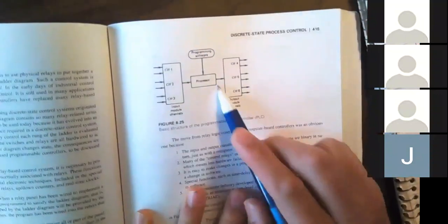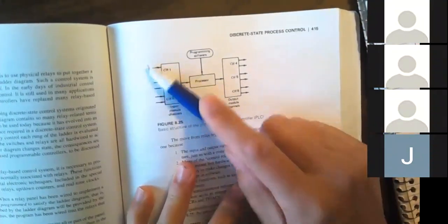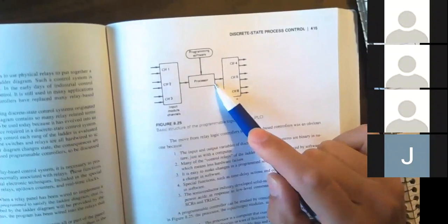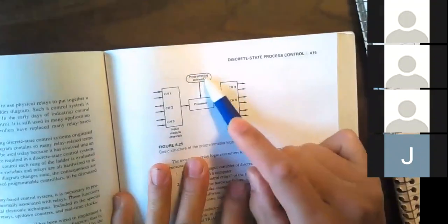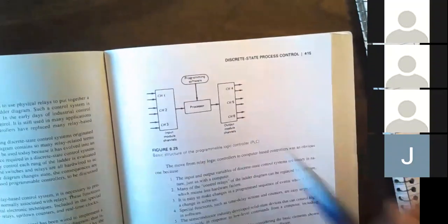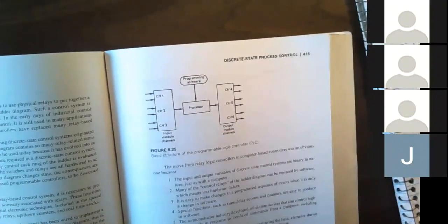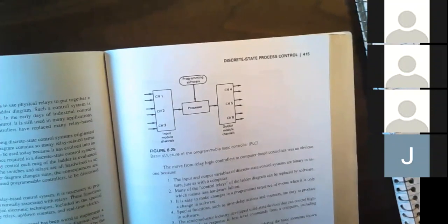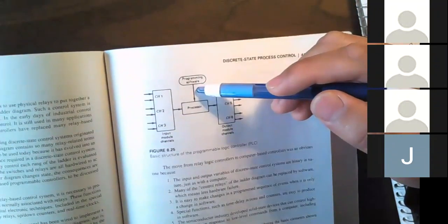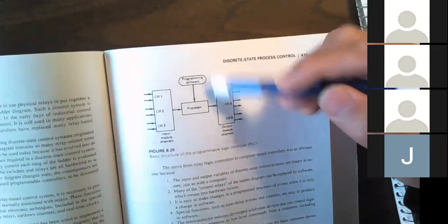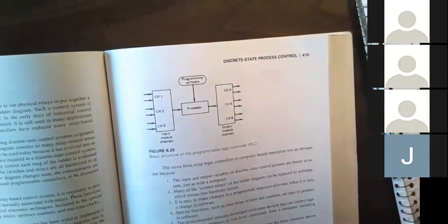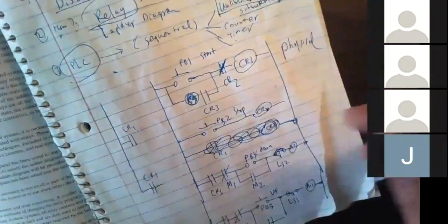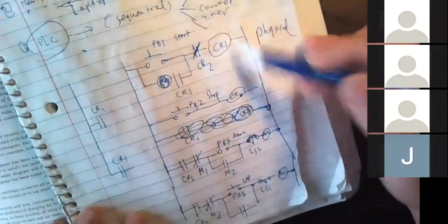So this is a typical PLC. In the center is a computer, and then you have inputs and outputs. Input and output, and computer. Then most importantly is the programming software. This programming software, because the control engineers, like I said, are not computer engineers. They do not want to write C code or assembly code or Java or whatever code. They don't like programming. So basically they use the ladder diagram. So that is the programming.